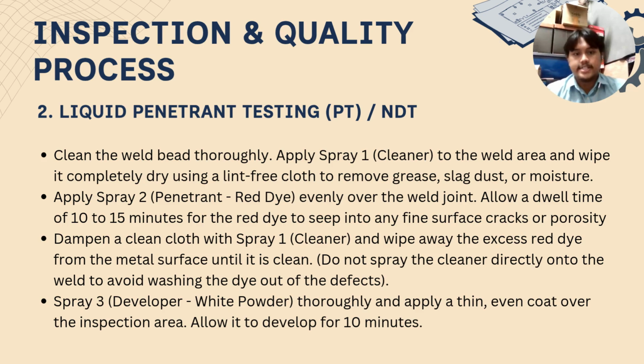Okay. The second method is liquid penetration testing. For the first step, we clean the weld bead thoroughly by applying spray 1, which is the cleaner, and wiping it until dry with a lint-free cloth to remove grease, slag dust, or moisture.